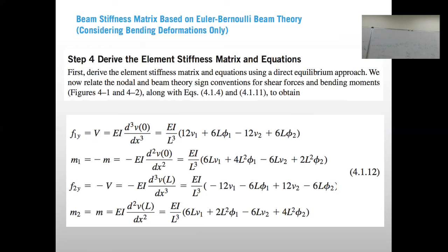Okay. Now, how do you go from the shear to the deflection? We have a formula that the shear equals EI times the third derivative. What is the moment? EI times the second derivative. And you put the minus sign, okay? Now, how do we do it? I only want the first one. Can you tell me? Go to the basic V, right? What is V? V equal to, yalla, V equal to what?